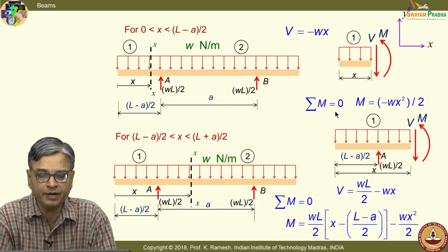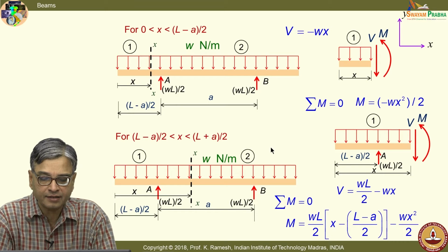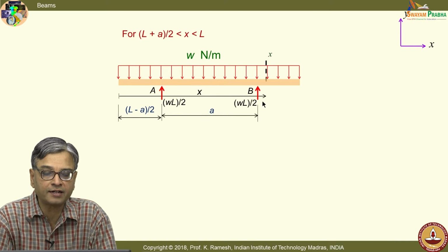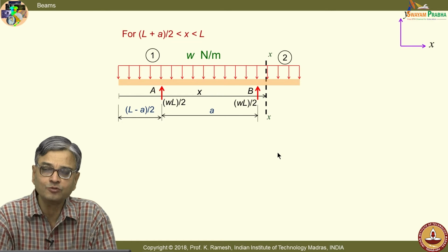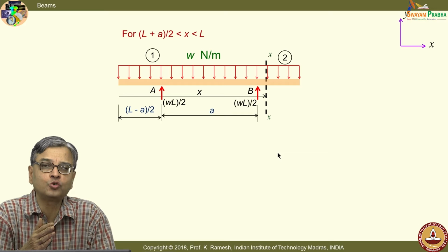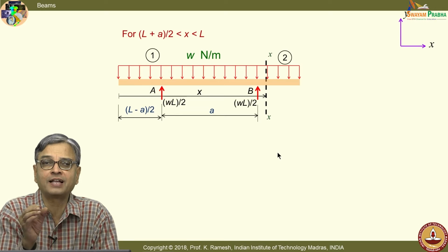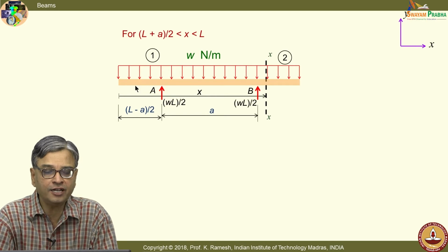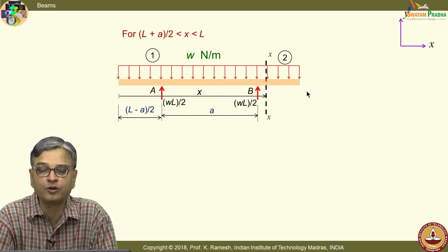expression for shear force and bending moment, and in between the supports I had made a cut and I determined the shear force as well as bending moment, and I would also make a cut at this portion of the beam and write down the equations. So, I would take a section like this, and this is what I said, you have a freedom to choose which portion of the imaginary cut you will take it for finding out the forces. In the earlier two cases, we had taken the segment 1 for analysis. In this, the mathematics is lot simpler if I analyze the segment 2.